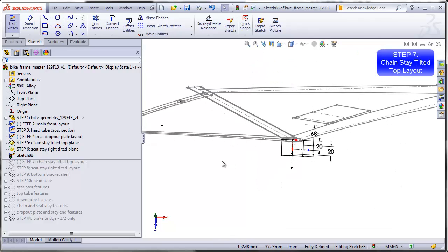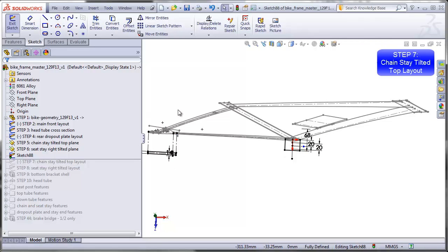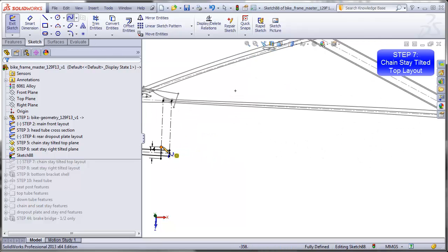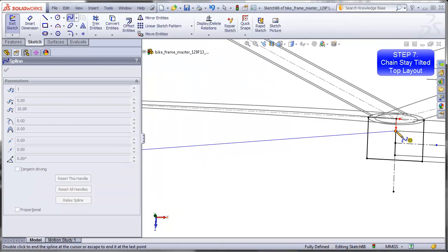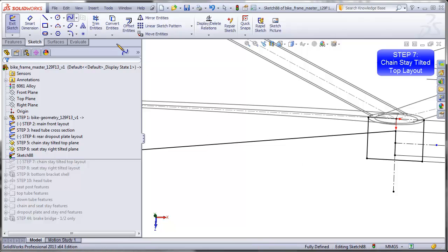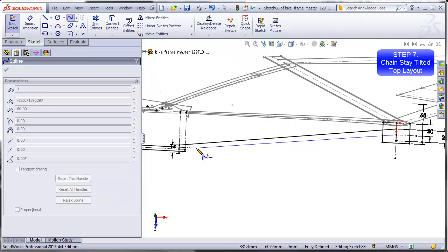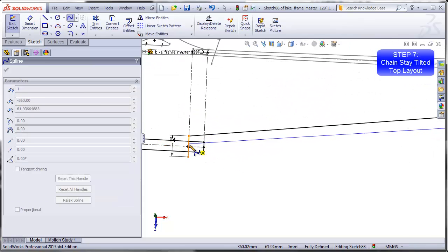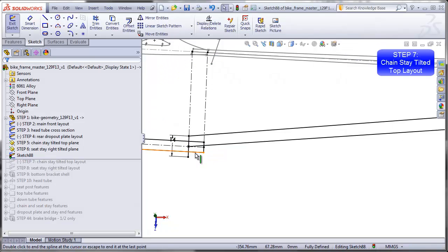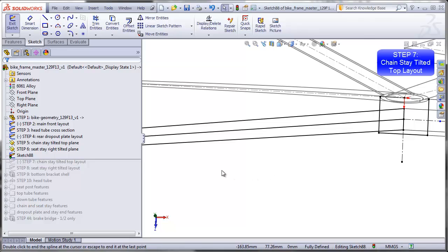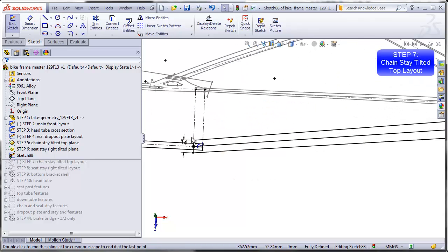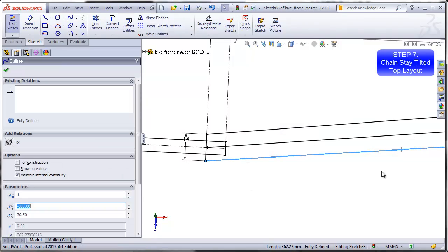Now I can start drawing some splines that connect this end to this end. So I'll start with the inside guide curve going from this point here to this point here. I'll draw the middle guide curve, which actually represents the upper and lower guide, going all the way to this point here. Finally, the outer guide going from here to here. Right now these look like straight lines, and I'm going to start tweaking my handles for these splines.